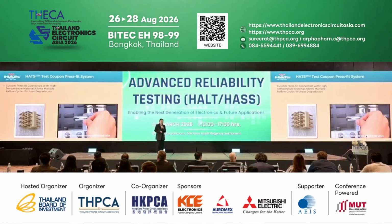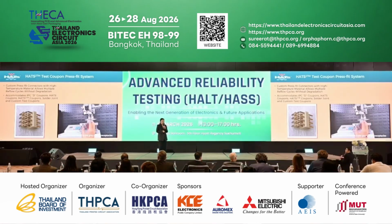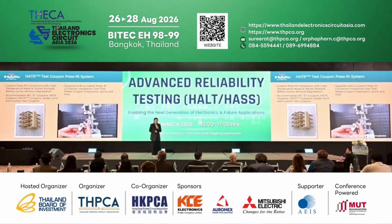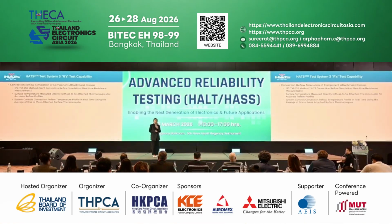Now we use custom press-fit connectors with high temperature materials. Easy to adjust. And it's plated with gold, so all the resistance is very consistent. Nothing additional contributes to the resistance measurement.